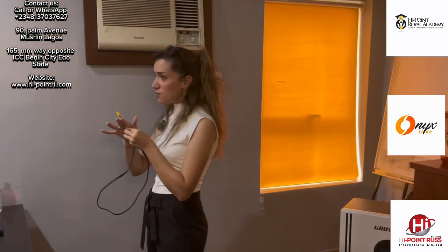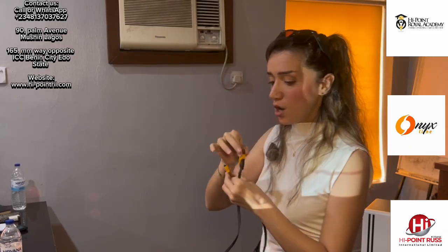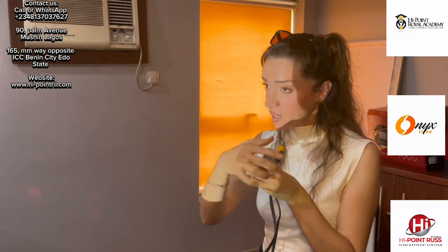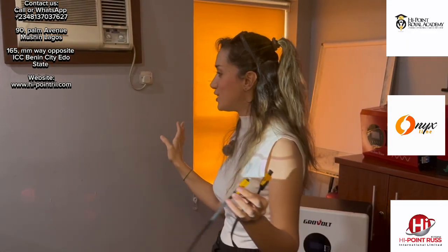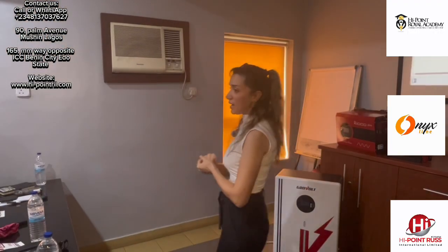You will cut the cable and bring the crimping machine and the new RJ45. You will put the cable from the battery side on pins 1 and 2, then you will clamp it. On the inverter side, you will put it on 5 and 6 and clamp it. It's easy. Okay? Okay, that's all about the Ragnar.